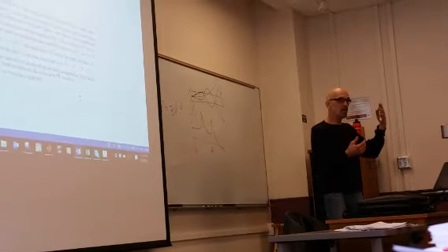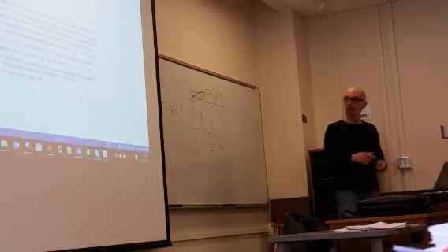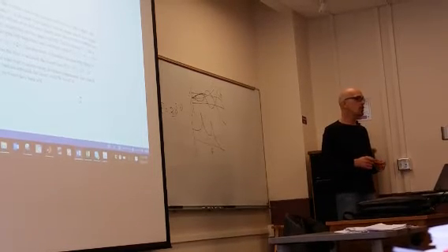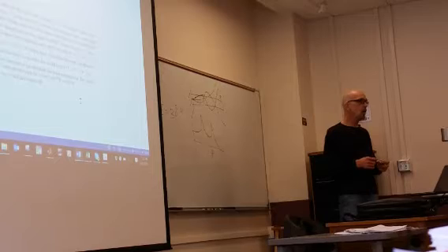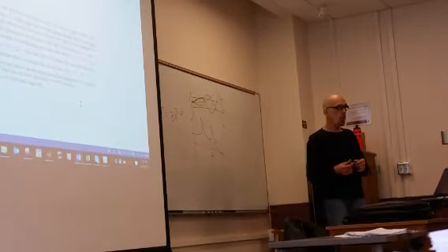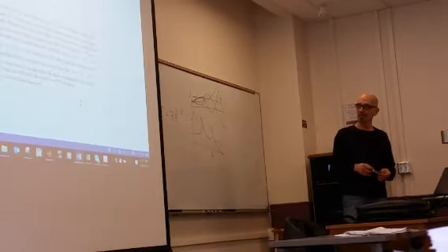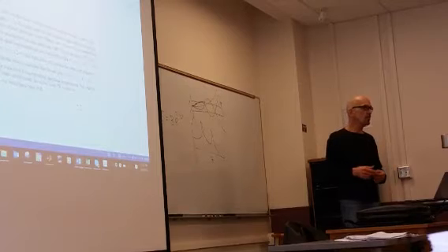It's a wacky function in s. It has infinitely many poles. And so the problem there is you can't use the root locus very easily, if at all, unless you approximate e to the minus st for small values of omega, and then you do derivatives and stuff like that. But this method is trivial.